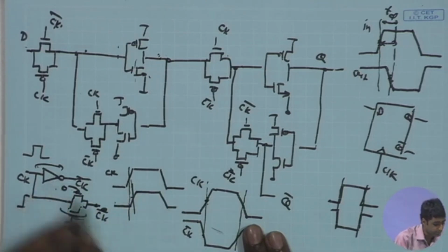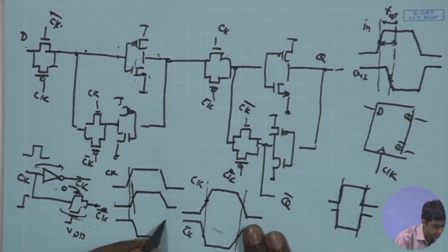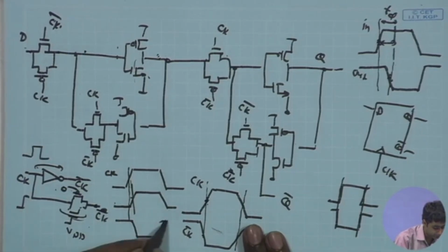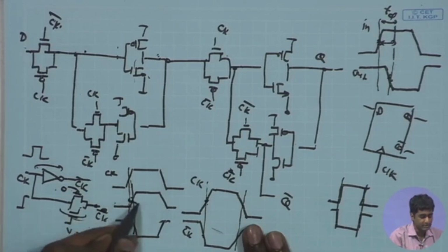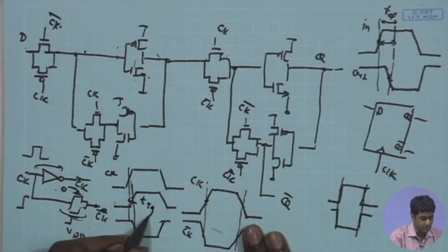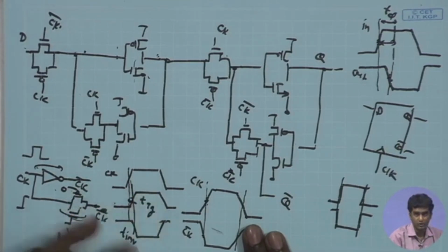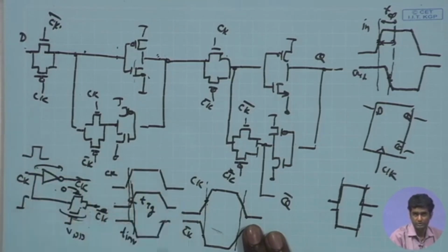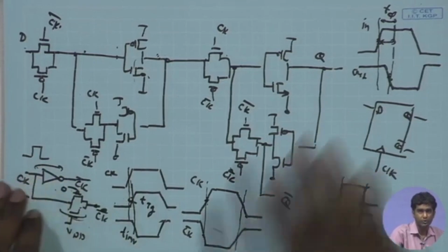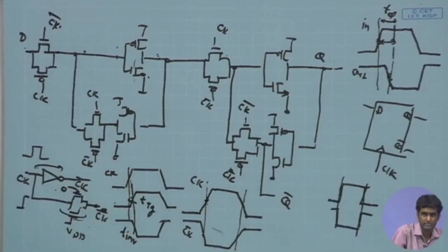Likewise, the inverter output will also be a little delayed and inverted, and once again the delay corresponds to the midpoint. So, what we expect is that the TG delay is equal to the inverter delay, so that the generated clock and clock bar do not have a shift with respect to the transition points. This is another point we should note while generating clock and clock bar from a single signal in a circuit.